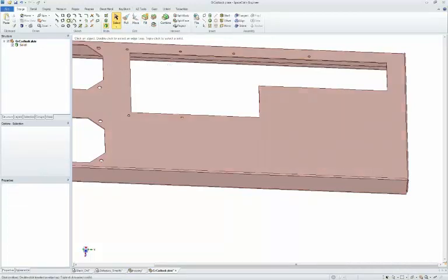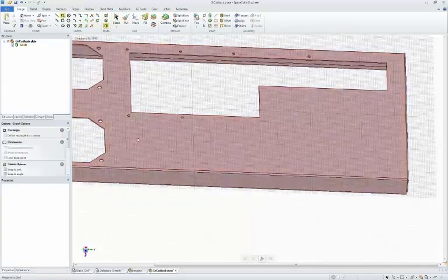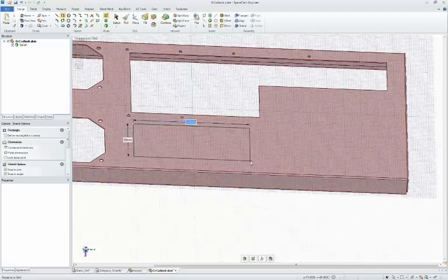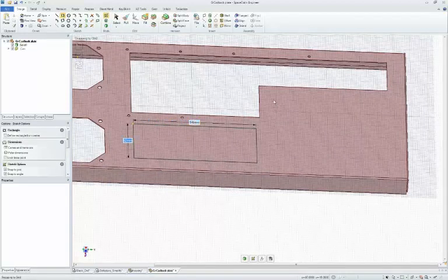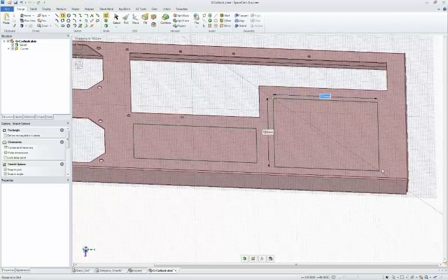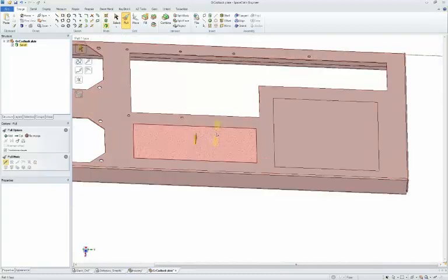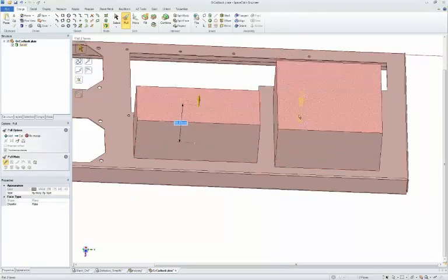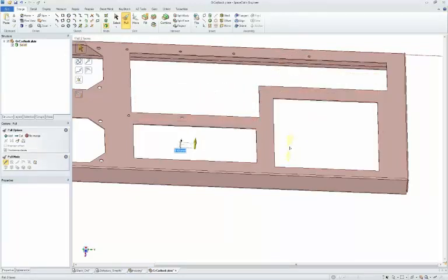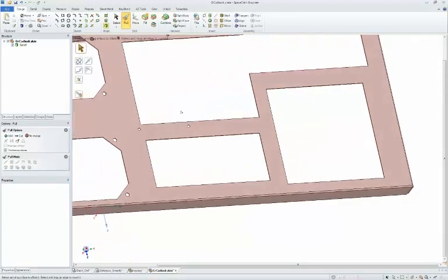And now I might not want this to be a solid plate though, for weight purposes and for how structurally sound it is, or maybe just for allowing for doing a thermal analysis or fluid analysis. I might want to create just a region for things to pass through, or just to remove some material. Sketch anything you need, pull anything you need. That's the whole part of it, is that you have easy tools to create geometry when you need to create geometry, but also edit incoming geometry how you want.